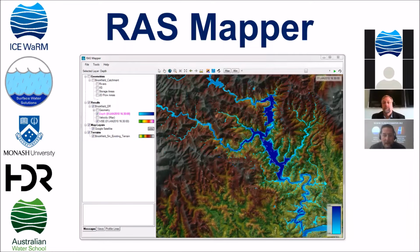So with that, again, we go through a lot more of these exercises in our course. We're going to actually talk about in RAS Mapper how to take any 1D model, any shape you can make in a 1D cross section and cut it through, like civil design software, through the terrain data. And once we do that, you can make any shape you want out of your terrain data. You can manipulate it, you can put in building pads, levees, dams. You can actually build your terrain data any way you'd like to see it and get very creative. So we do that in the course.